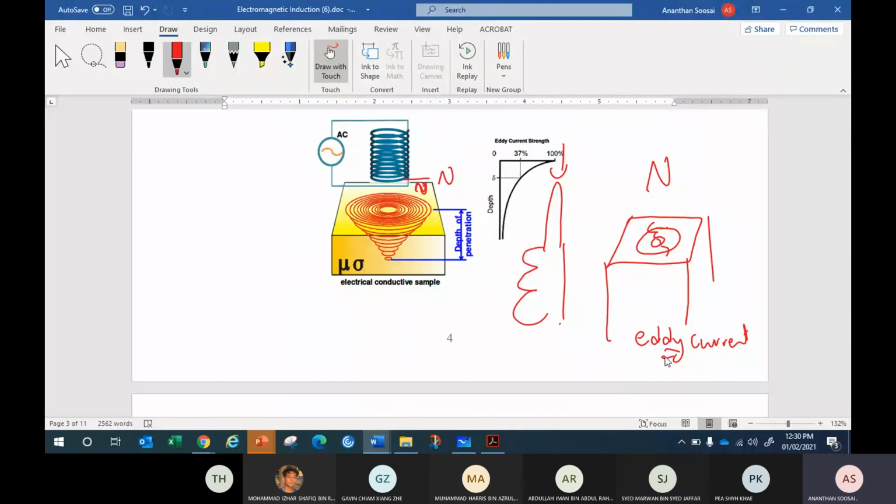Okay. The term eddy means circulating current, used in liquid, like a circulating movement. So this is called eddy current, moving in a circular path. All the electrons are going to move in a circular path like drunken electrons, to generate the north pole. This type of current is going to give a heating effect to the material, because current is flowing, heat will be generated. It will heat up the body, and might slow down any movement.